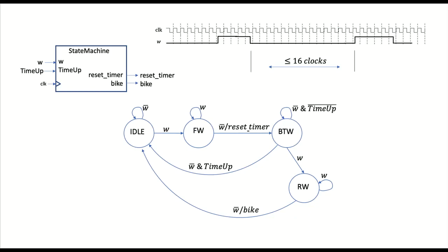So the slash after RW, that's when W goes low, slash, that means you're sending an output to something that's not actually part of the state? Right. So this is the notation where you have the condition and then the slash, the output you want on that arc.